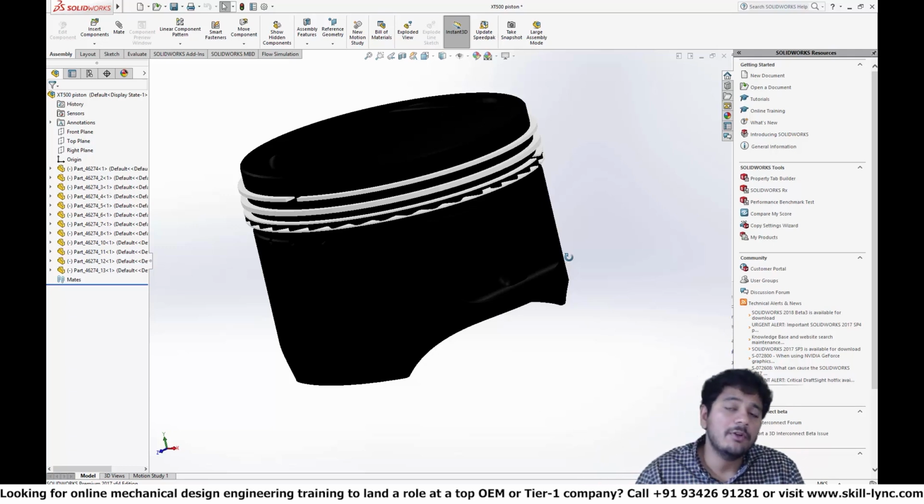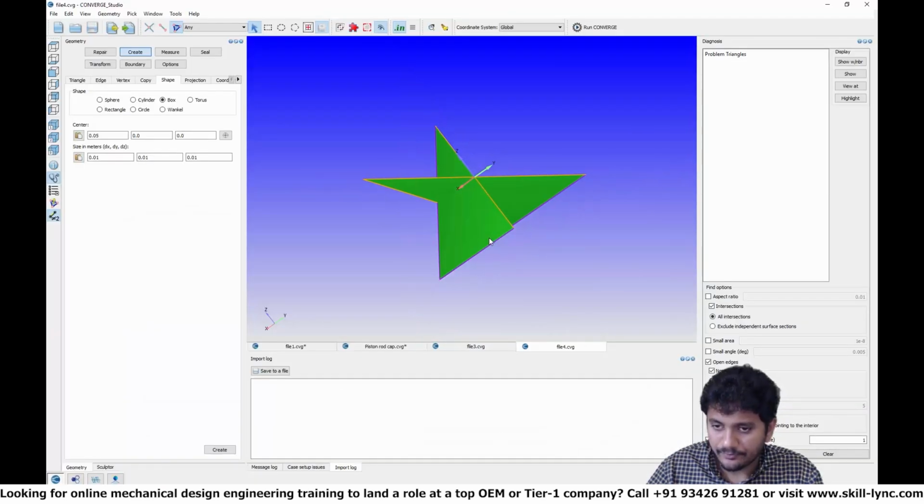So what people do is they either have powerful surface meshers that can convert a native CAD file into STL files, but the trend in the industry now is that all of the major CFD players have incorporated the ability to read in native CAD files. So you can read the CAD files in the CFD tool itself, and it's going to create a perfect triangulated mesh which will have fewer problems. Okay, all right, so that being said, let's go back to Converge Studio.